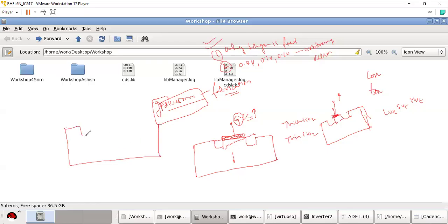In this MOSFET, I have these two P wells, N wells, and on this N well you have a layer of SiO2. Here you have a gate. The process is that you give some gate voltage, and this gate voltage attracts the electrons and forms the channel over here, right? When will the gate voltage required be higher, if you make the SiO2 thick or if I make SiO2 thin?